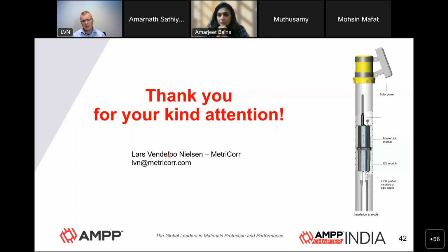So if you think that a coupon is not representative of a pipeline, I usually say back, well, in terms of evaluating cathodic protection, a simple measurement on the pipeline does not represent all the coating defects that you have on that pipeline. Whereas a coupon is a mimic of the worst case condition, and then you establish that worst case condition and measure according to it, and that would be your strongest argument for using a coupon.